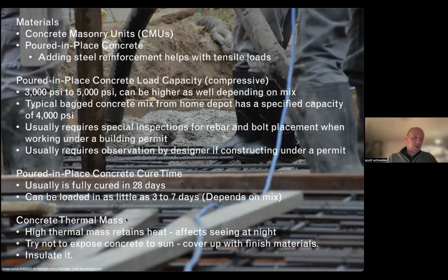One of the things about concrete is that it has a high thermal mass, which is counter to what you want in your observatory, because concrete can absorb heat during the day, and then at night it lets the heat off slowly.